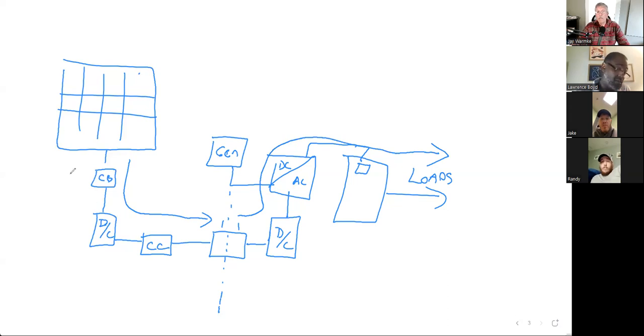You're drawing power from the battery and servicing the load, just like with your laptop. I turn on my laptop, it pulls power from the battery and services the load. I don't have a solar array connected to my laptop. If I don't have both, the system doesn't make a lot of sense, but they are acting independently of each other. The array charges the battery and the battery services the load. Everybody follow that concept? All of the power servicing the loads gets pulled through the inverter from the battery.